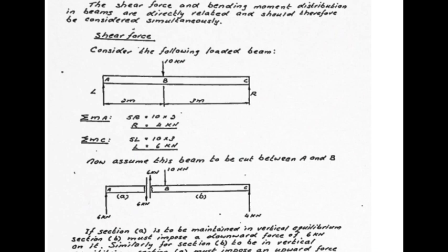And we're going to start with this very simple beam ABC, which is loaded at a point somewhere along its length, 2 meters from the left-hand edge, with a downward point load of 10 kilonewtons. It is simply supported at A and at C. The magnitude of the left support reaction at A is L. There's an upward arrow there and an upward arrow over there.